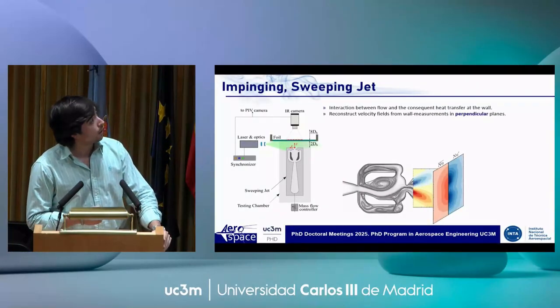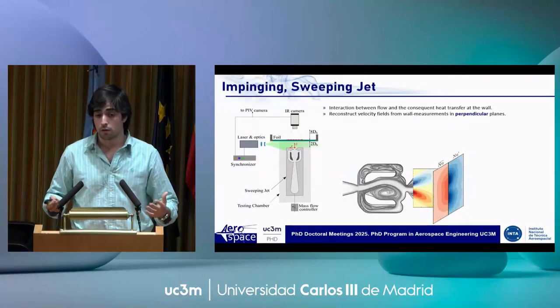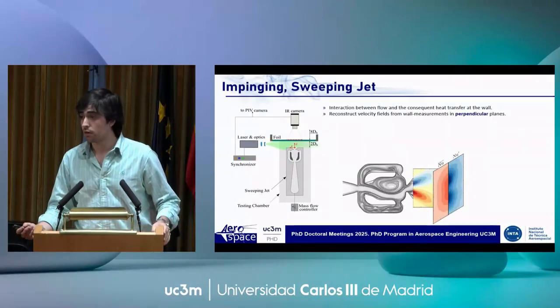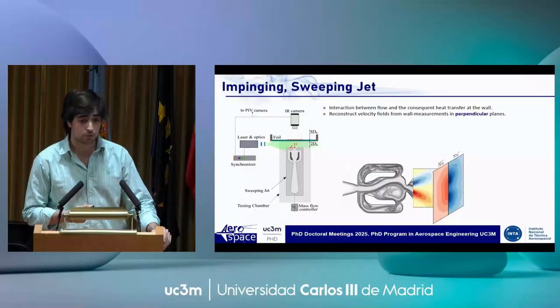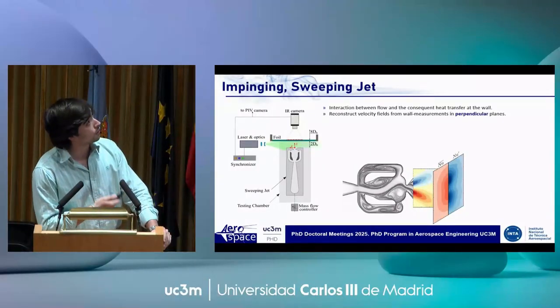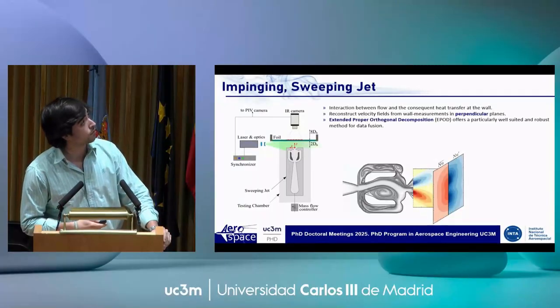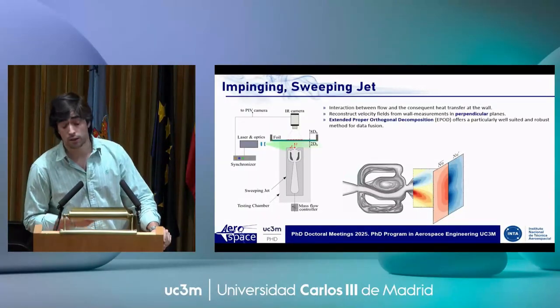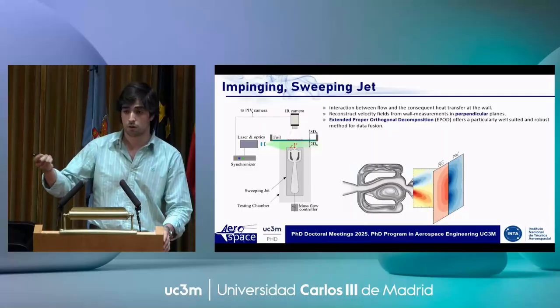However, we do not have time-resolved particle image velocimetry equipment. So the first objective of this experiment, in line with the objectives of the thesis, was to reconstruct the velocity fields from the wall heat transfer measurements using the extended proper orthogonal decomposition we have talked about before.